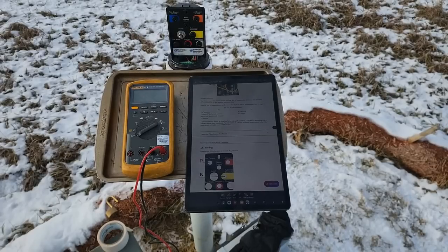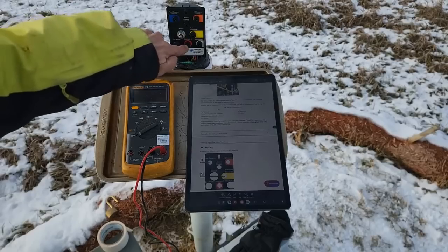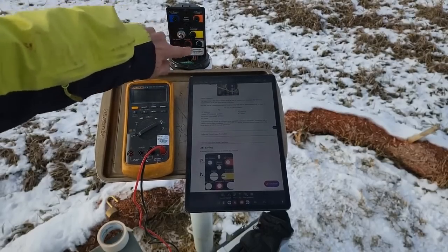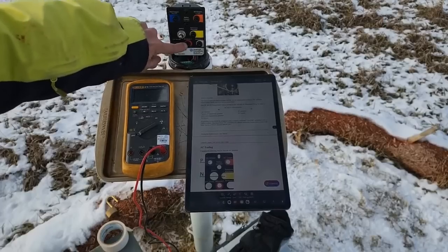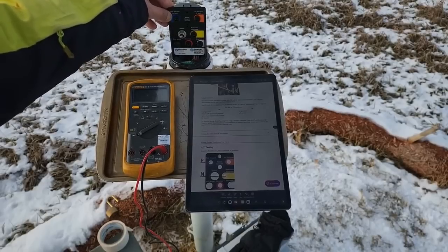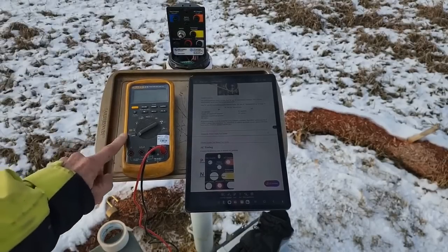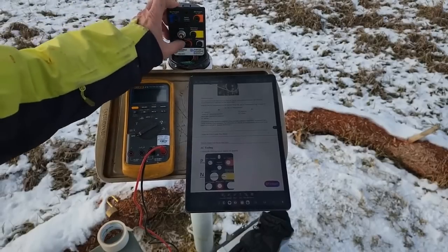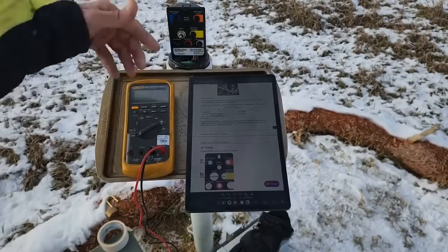We won't use this coupon, only the orange. One is used to measure current. But when we go to measure currents, we'll connect it to the structure. That is, the structure number 102. And we'll set the multimeter to milliamperes and interrupt the switch.